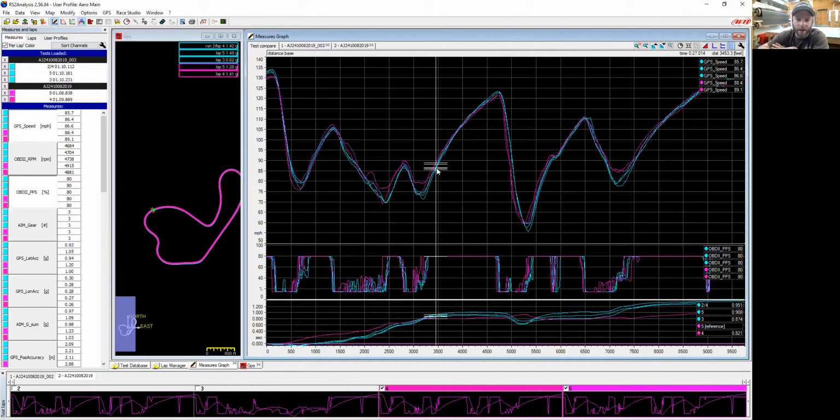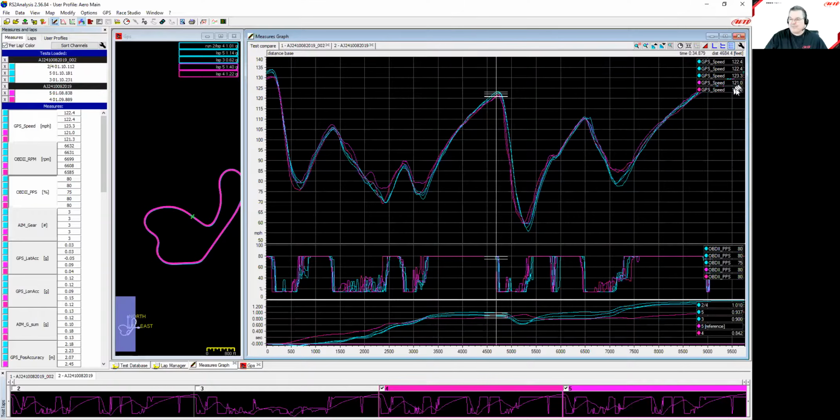Yeah, and then here where you're still at 85. So this entire area here between 70 and 95 through this series of S corners and entering the cornering force part of that corner, it's almost a second of time that the car would do. And now we're talking same driver, same tires, just these aero aids that you did here, right? And you can see the loss. And then what's interesting is now you're going down the straightaway, and it flattens out immediately. And actually, if you look at the data, the red has higher exit speed, higher, you know, 20% of the way down the straightaway, and then the lines cross. And you get up here to the end, and it's 122s, 123s, and 121s.